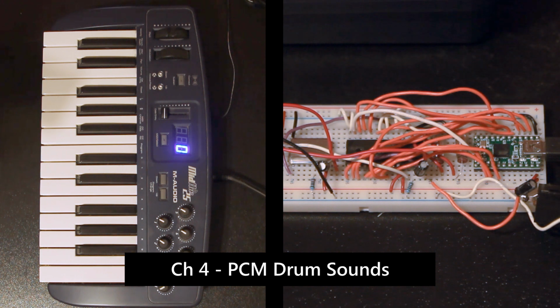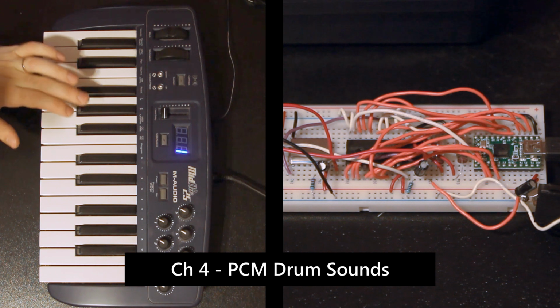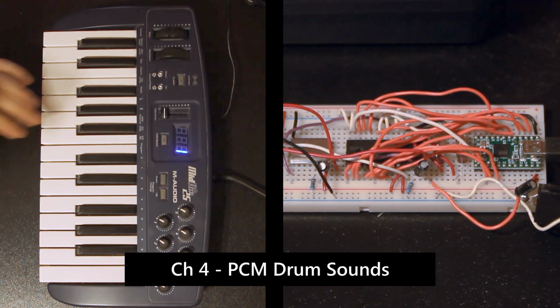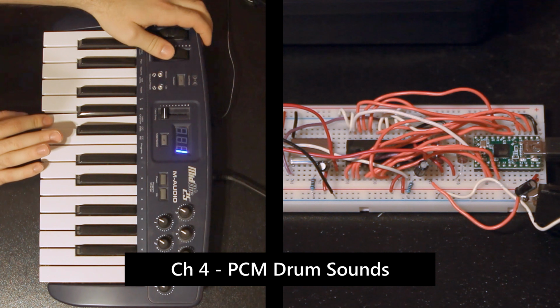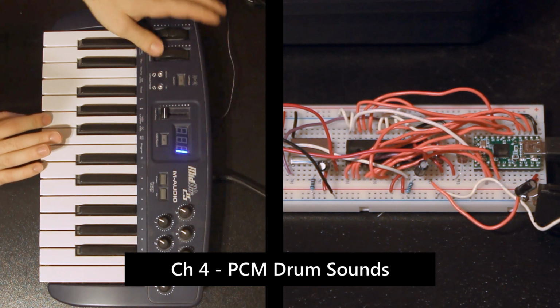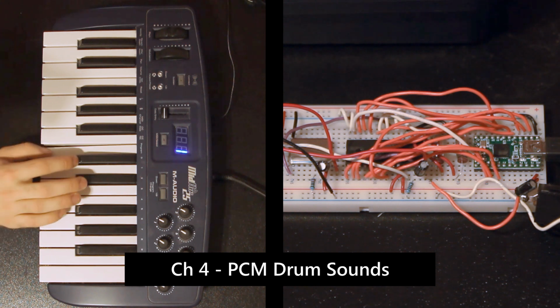MIDI channel 4 plays drum samples, which is traditionally done on this chip by putting a DC offset onto the filter and then adjusting the filter volume for each sample. I have PCM audio embedded in the code itself. The mod wheel and pitch wheel change the sample rate. And I also placed some of the sample addresses in the range of the actual program data.